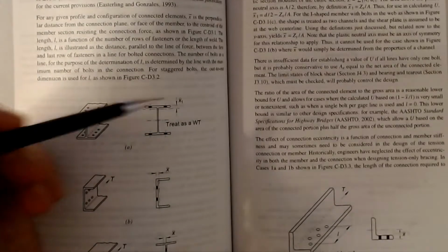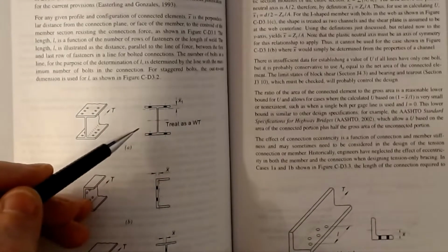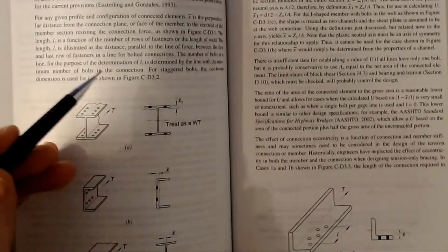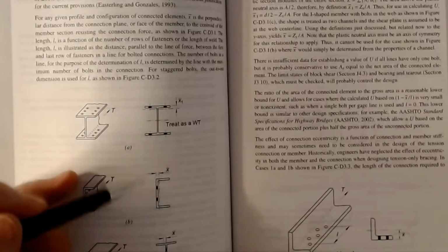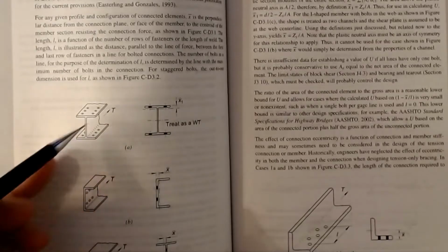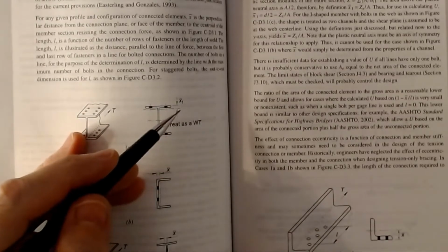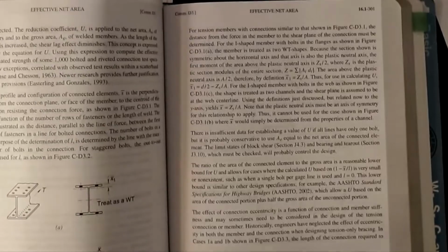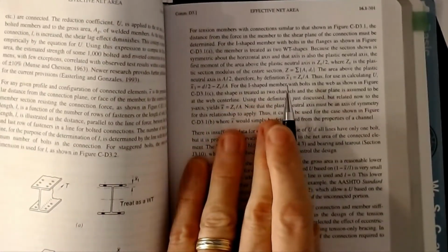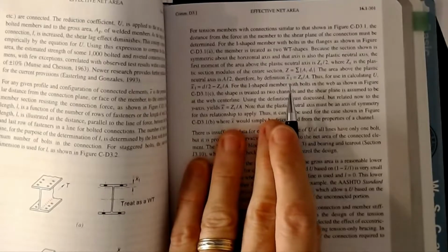Okay, and so what they say is you take an I-beam and you cut it in half. So that kind of goes with our assumption that the upper part takes the upper load and the lower part takes the lower load. Again, right or wrong, that's the way it's treated. Okay, and you treat it as an equivalent WT section. Okay, and so the way that you calculate X1 bar then is actually spelled out for you over here in the paragraph. So you've got to read through a lot of this. Okay, and so this is exactly what it's saying.